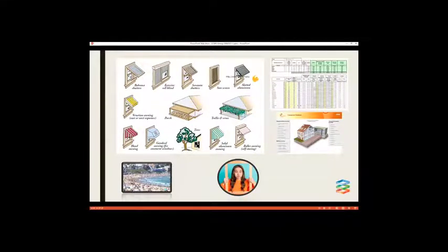And when you actually go in and have a consultation with a Passive House consultant, they will input all of your windows, same as what an energy assessor would do, into the PHPP. And you put in all your shading, your frames, the entire window system, and how it's installed in the wall is actually calculated to become more energy efficient. So that is really important, that all of those things are looked at.